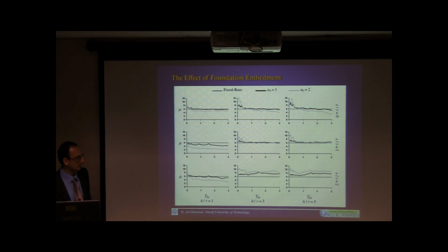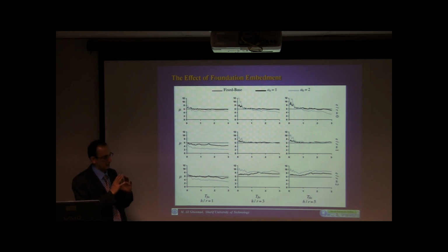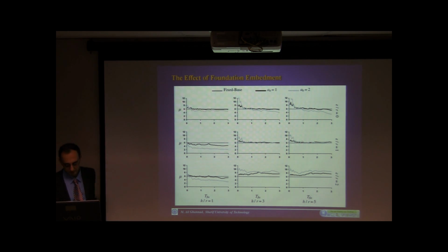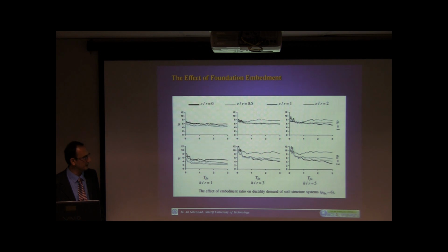But I'm talking about that because in the current provisions, we don't look at the rocking input motion, but we look at the reducing effect of kinematic interaction by filtering, by slab averaging. And the results can be different from the real cases.